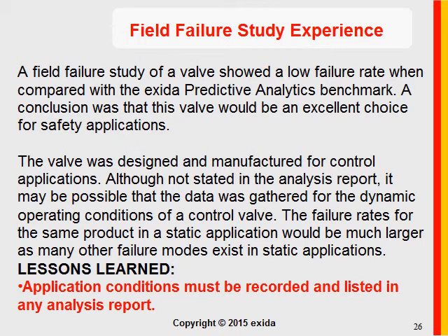So you might think of this whole process as a closed loop feedback mechanism. Validated field failure data must be used in an FMEDA to get realistic results. Exida definitely has a very detailed paper talking about how we constantly compare FMEDA results, predictive lambdas, to the validated field failure data that comes from the field. You kind of saw that on the slide, but different emphasis.